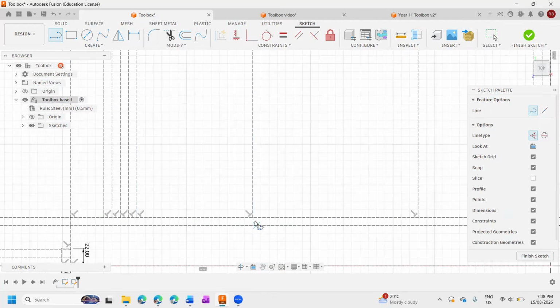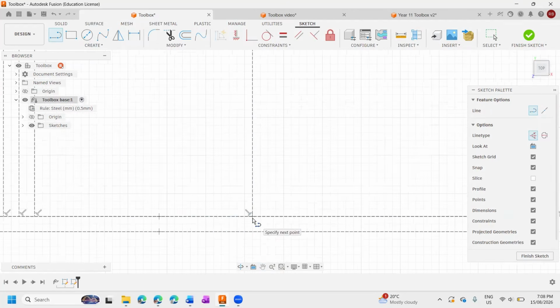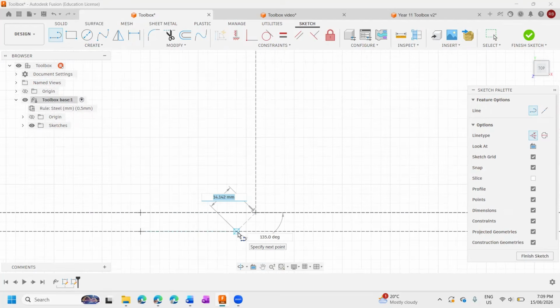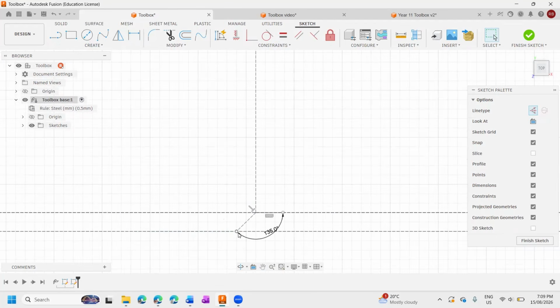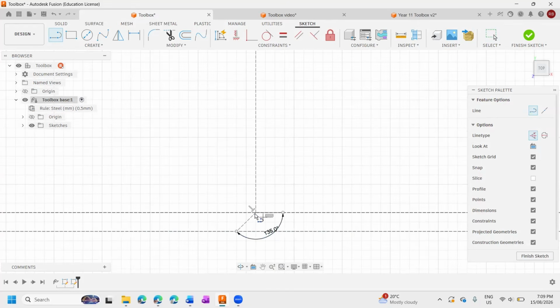All right, we're going to do line. We want to have kind of like that angular shape coming from here. So I just want to press the middle, bring it out. So see how we've got the measurement and our degree. So remember we press tab to change over to the other type, which is actually 135. So it'd either be a 45, a 90 degree, or 135 is what you'll typically end up punching in there.